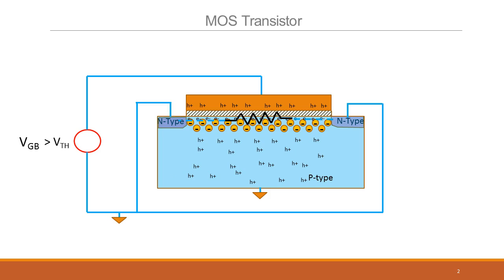So let's say we ground this other terminal as well, and you bias one side of the new contact that we have put in through a VD. Let's say we increase the potential of this side relative to this side and apply a positive potential VD. Now we know there's a resistor here. So what should happen ideally? You will have a current flowing through this, because of the VD that you have put in here.